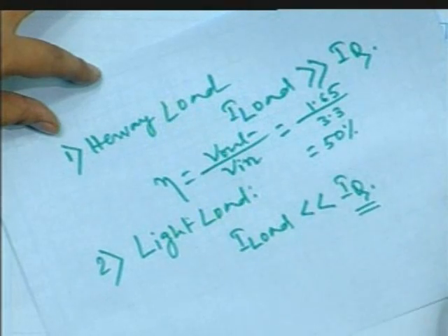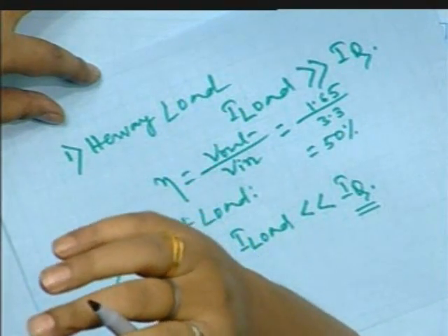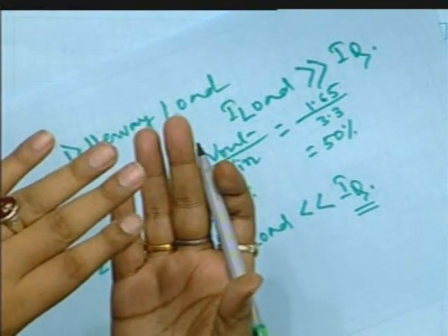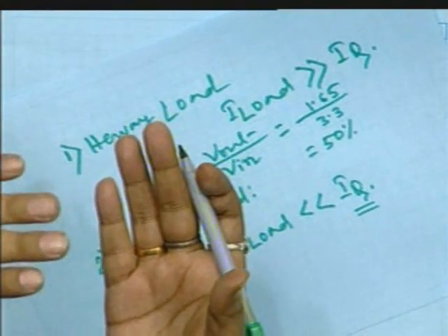So, you can see that if the dropout voltage is more, dropout voltage meaning the difference in voltage between VDD, that is the supply voltage, and the output voltage, your efficiency will be poorer and poorer. That is why linear regulators suffer from poor power efficiency. And we will go for the LDO type of regulator. I will come to that point.